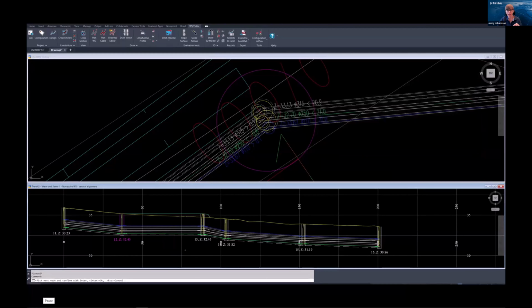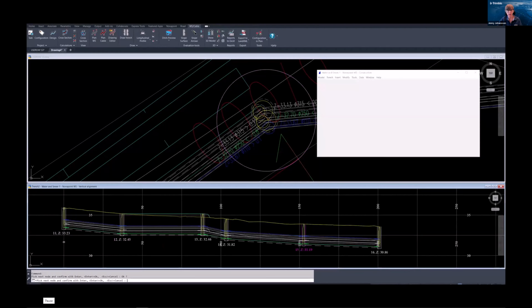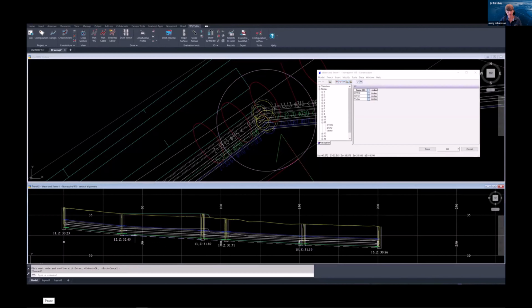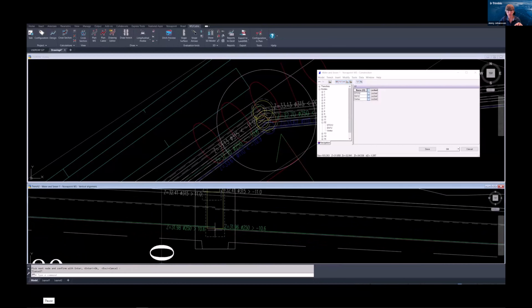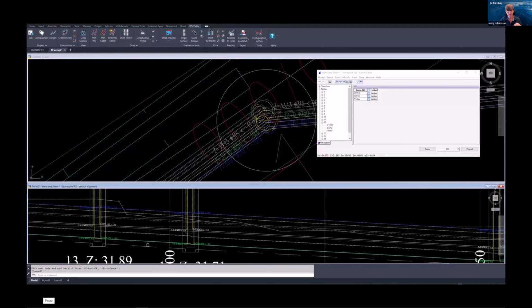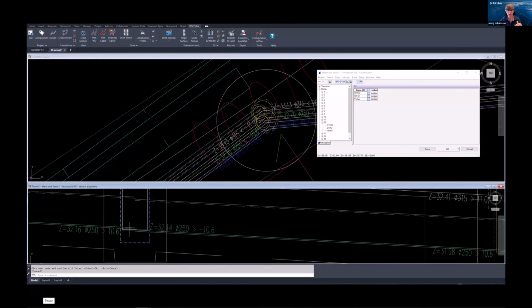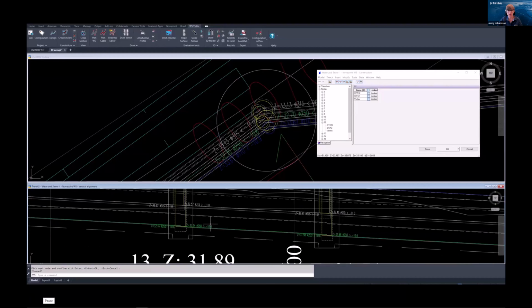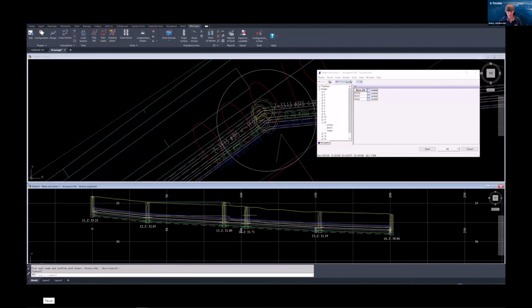After that, I select the end node, in this case, number 15, and when finished, I will get the same slope the whole way. When doing this, we can see that the difference between pipes of 2 centimeters will remain, but the manhole bottom will be set following the trench bottom and the interpolation.